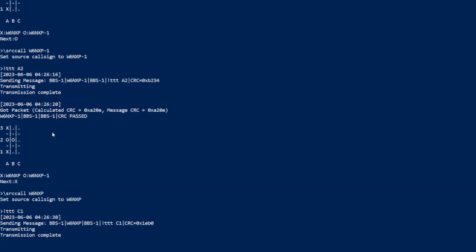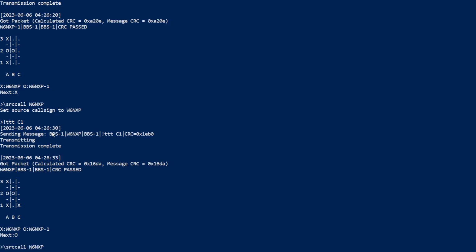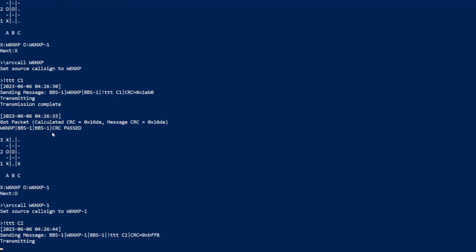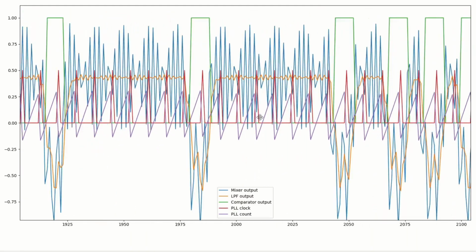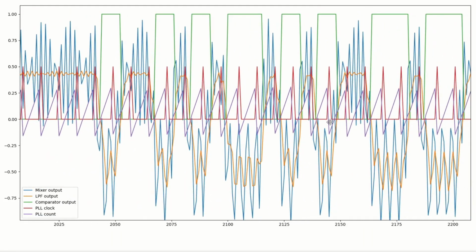To communicate with the server, I wrote a Python script to implement the same modulation and demodulation routine as on the microcontroller. This was also useful for verifying that the demodulator worked before porting it to embedded C.